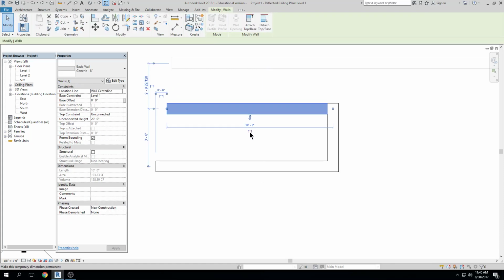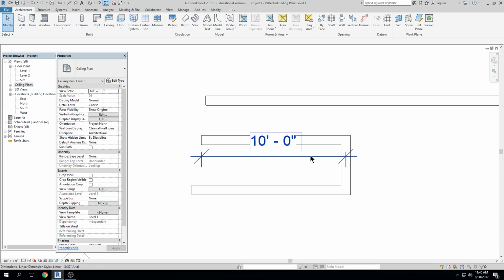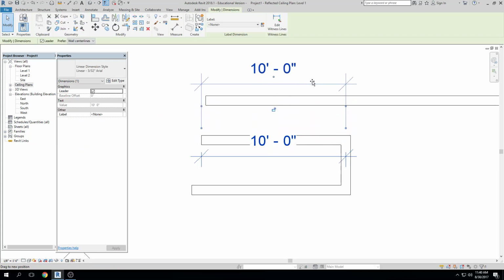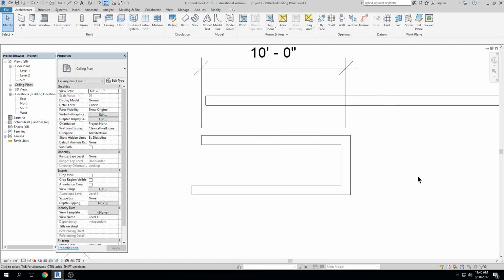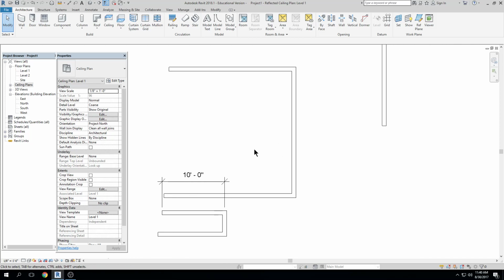What's also nice is that you see there's this little grip-like object underneath the dimension. It's temporary and it's blue unless I want it to be there permanently. And then if I click on this little dimension, click, it converts it to an actual dimension, as if I pulled it from using the dimension command. Okay, so let's look at this drawing command again in sequence.